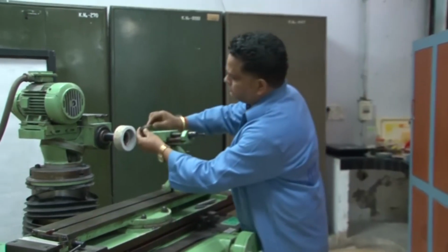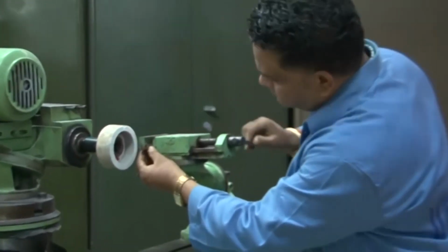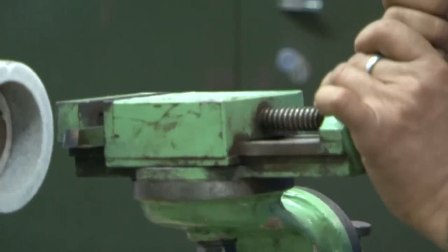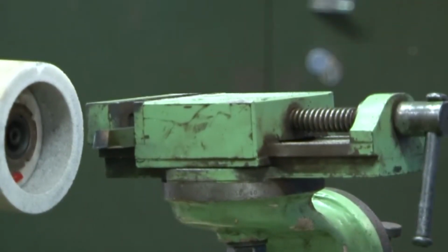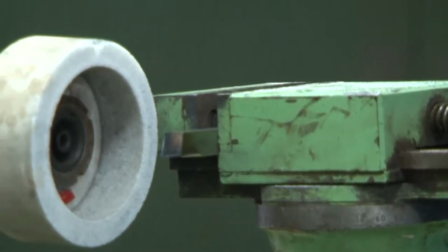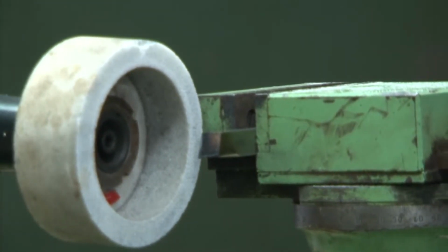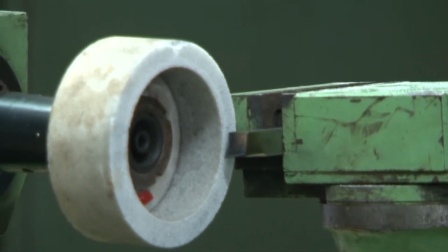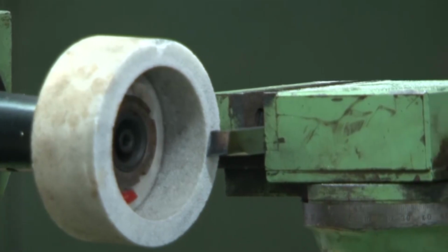The grinding process is required. Let us say the worn out tool, the one that I have shown you, is clamped in the vise, which in this case is the tool post, and the grinding wheel is already mounted on the mandrel. Now, initially you make the 0 point, that is, you touch the grinding wheel with the surface that you are going to grind,